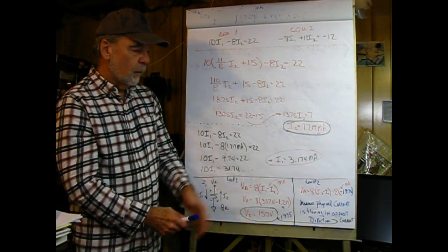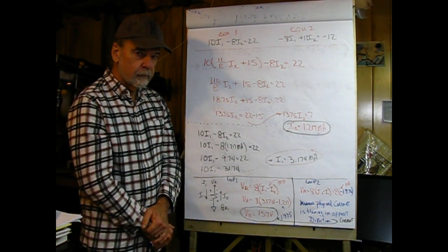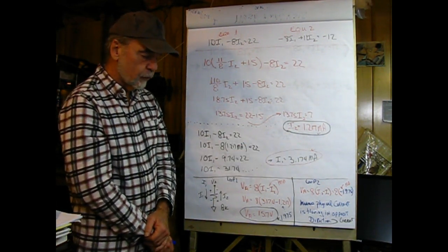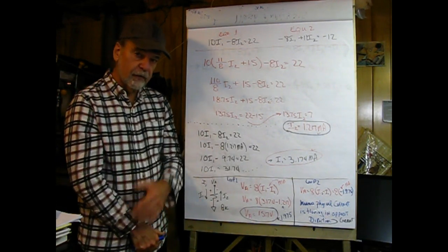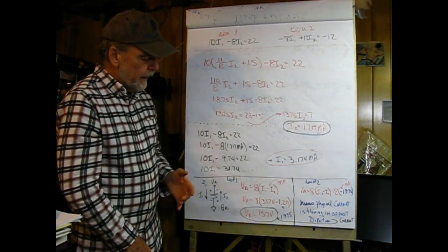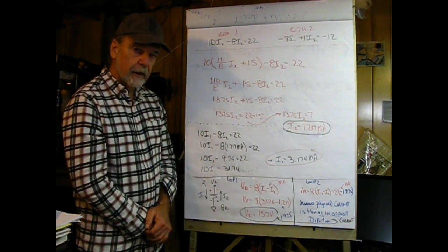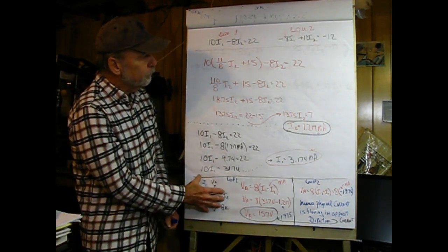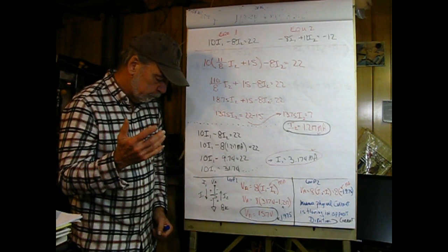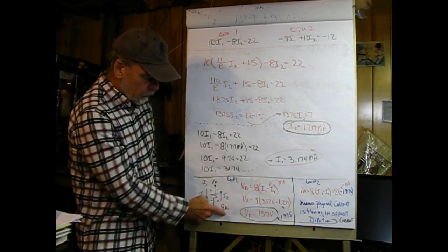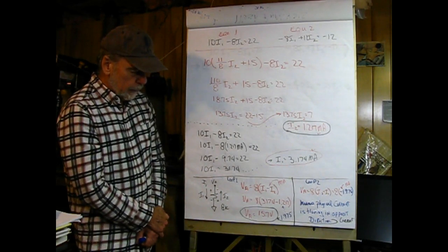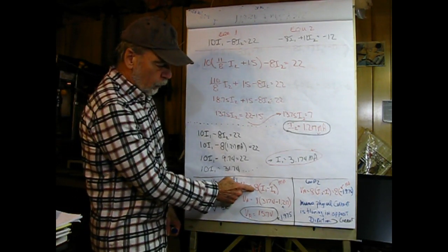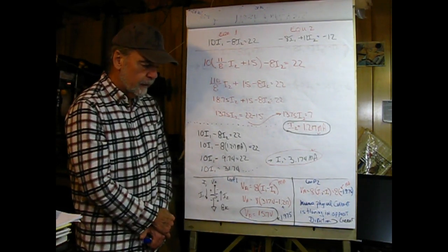So we've got our two mesh currents here, and this doesn't solve our problem. It gets us quite far along, but to solve the problem, what we have to do is find the physical currents, and the key to that is to find what the voltage is at VA. So I've taken from the original schematic this component of it showing I1 flowing down and I2 flowing up, and then I've written down VA equals 8 times the quantity I1 minus I2.